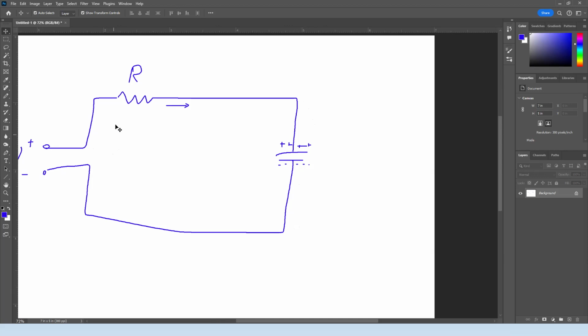So because of the inrush current, initially, when there's a maximum current flow, just like a piece of wire, of course the voltage between here and here would be 0. And as the capacitor charges, there is less and less current flow. It charges up, then the voltage is going to equalize: this point is going to be equal to this point, because there's no current flow.